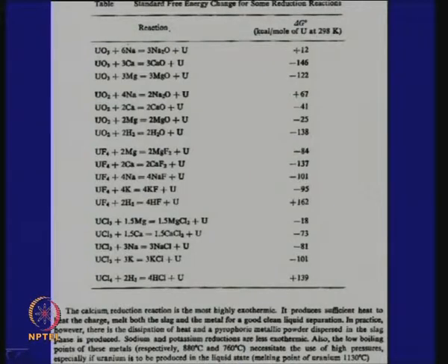You start with a low grade ore, you produce an oxide, 70% U3O8. You have to purify it further, then convert it by some simple chemical steps to pure UO2. You can chlorinate it using carbon and chlorine, or carbon and fluorine, to get either chloride or fluoride.